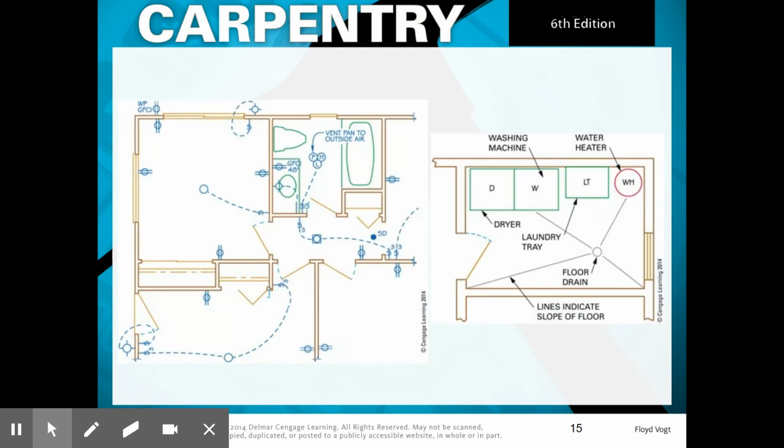So here's another typical floor plan. On here, we can see that this is a switch going to a light fixture, duplex GFCI. This is a vent, so you can tell that this is a bathroom. Here's your toilet or water closet, vanity, sink, bathtub, bifold door, another receptacle, 3-way switches running. So this one's going to a fixture here, as well as that one. Another switch here, switch to this light fixture. And if you look around, you could see more.